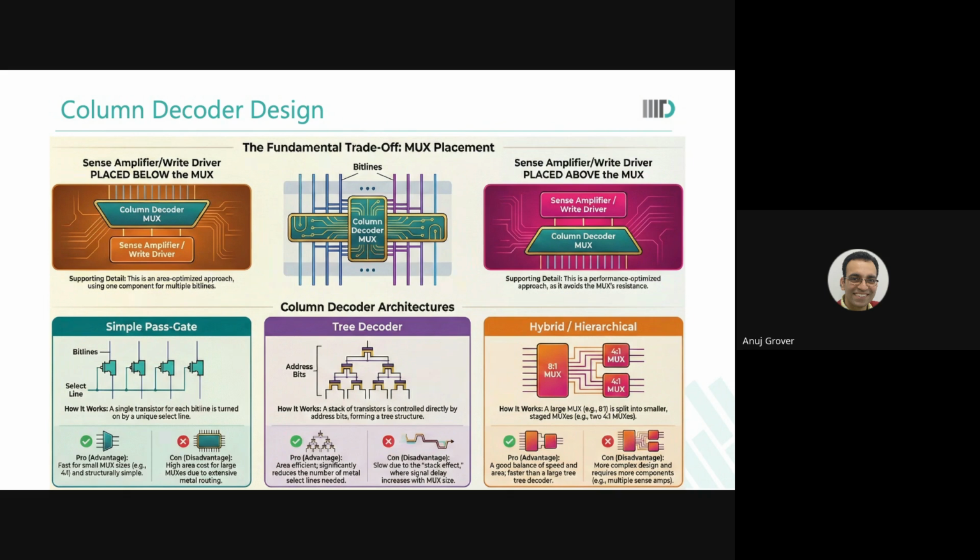Digital mux is using AND gates, NAND gates, and regular gates to do the multiplexing. That is how you did multiplexing in your DVD program, na? So that is digital mux. They're using PTL logic, so I will not call it digital mux. It's an analog mux in a way. It is transmitting even a very small differential from the bit line into the sense amplifier. For a digital mux, you would require the bit line to discharge to at least VDD by 2 to say it is 0 or it is 1.